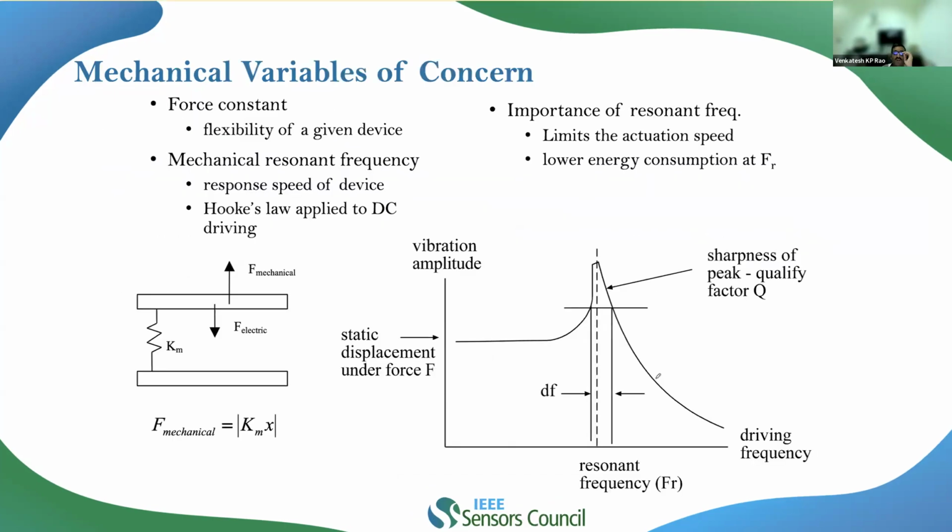And there are plenty of things you can get in the mechanical design of your micro resonators under consideration. The first and the fundamental thing will be the force constant. The force constant, which is basically the stiffness I told you about, will tell me how good the flexibility of the device under consideration is.